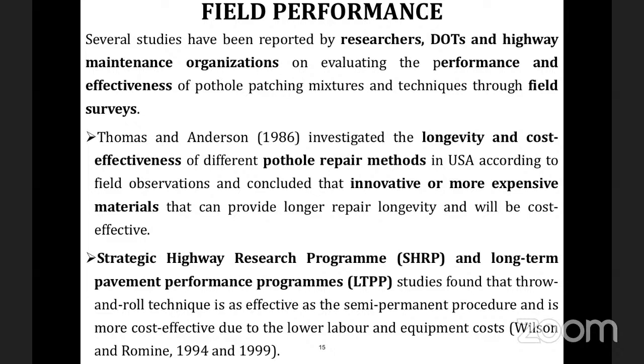In 1986, Thomas and Anderson investigated the longevity and the cost effectiveness of different pothole repair methods, that is throw and go, throw and roll, semi-permanent, and spray injection in USA. According to the field observation, they said that some innovative or more expensive materials can provide longevity and will be cost effective. Innovative or more expensive materials may be the binding agents. And the spray injection method or the semi-permanent procedure is one of the good pothole repair methods they found.